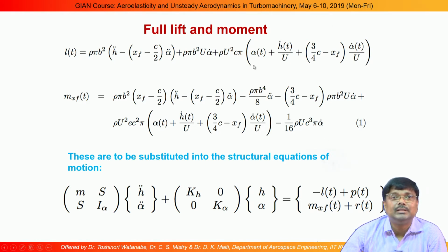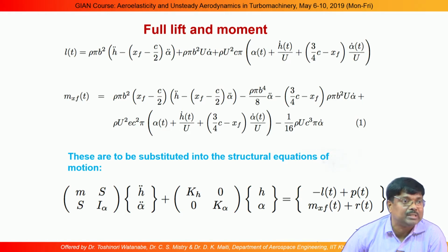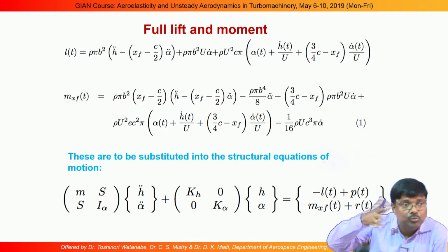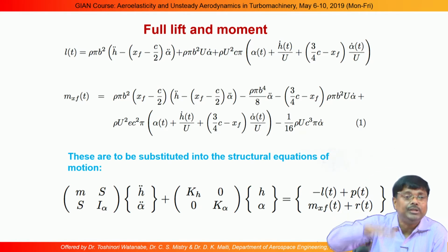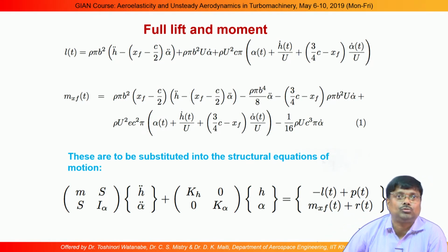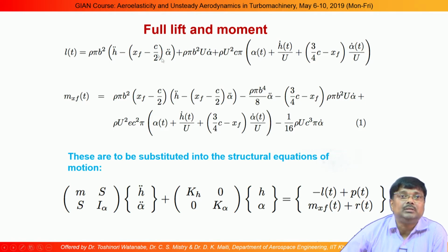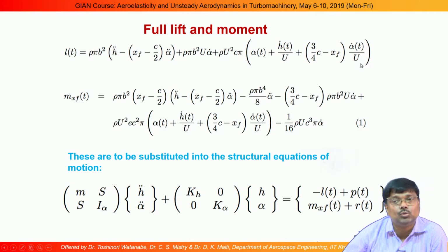This is the inertial mass and this is the Coriolis force, an inertial force due to rotation. This is only due to heave motion, effective heave motion, but it has effective rotational motion also, rotational acceleration. That is the Coriolis force, and what we are getting here is nothing but the usual quasi steady load. The same thing we have converted to moment also.